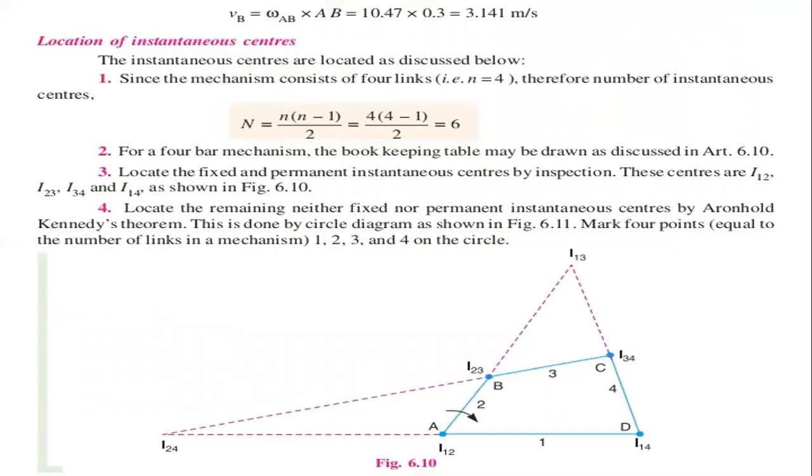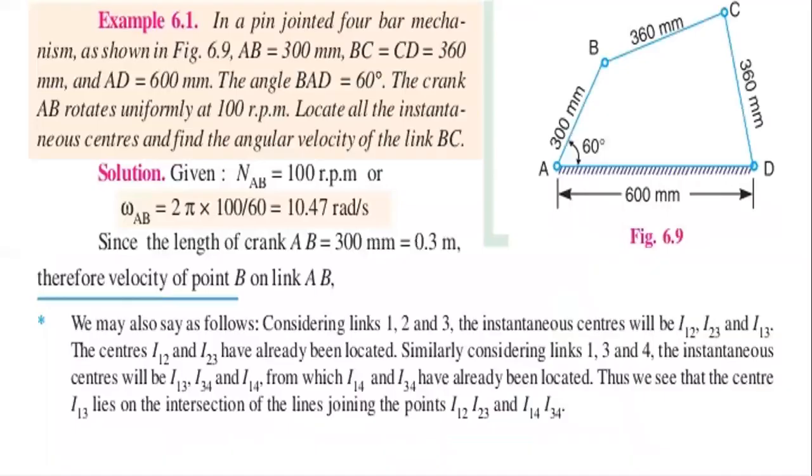So next we use to find the velocity of the point B. We have this formula from the earlier problems. Velocity of B is taken as angular velocity of AB into length of AB. Because here we are taking the B link, we have to take the length of A with respect to B position, that is velocity of B with respect to A position.